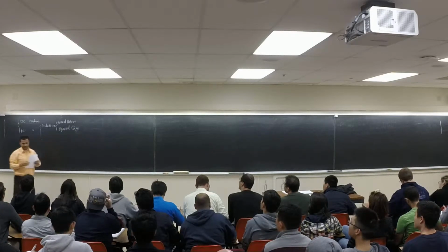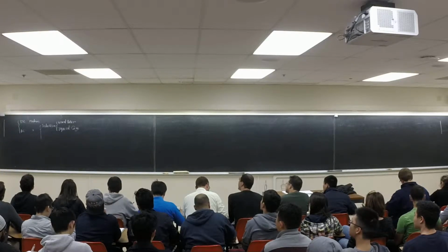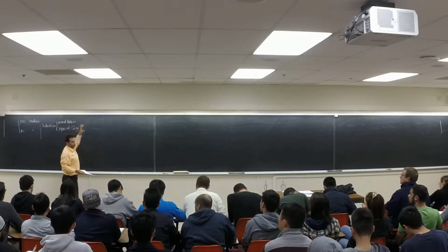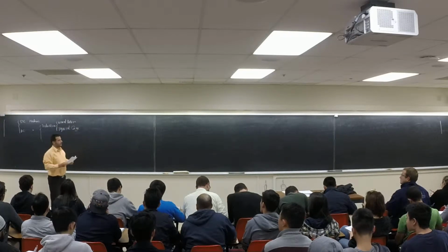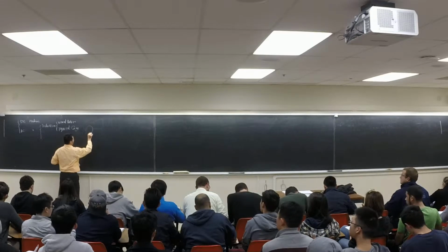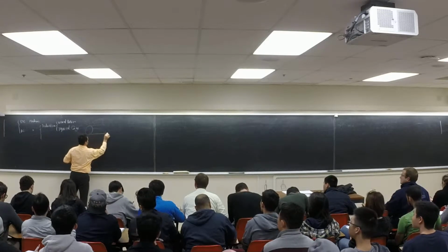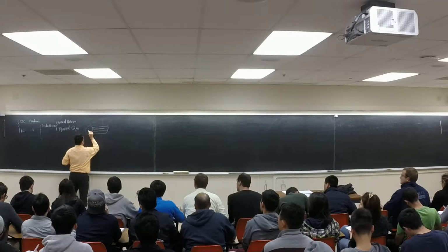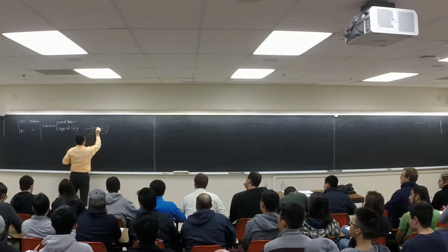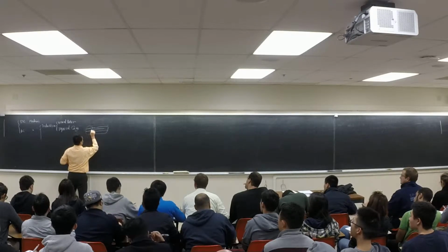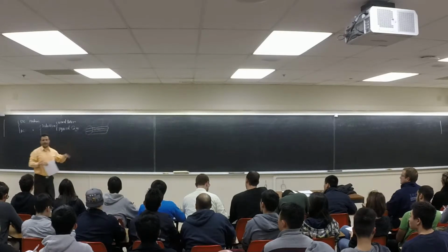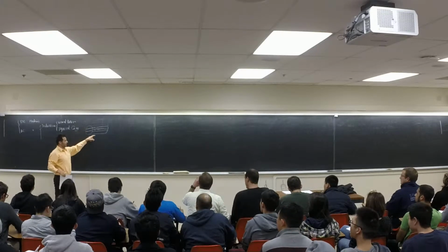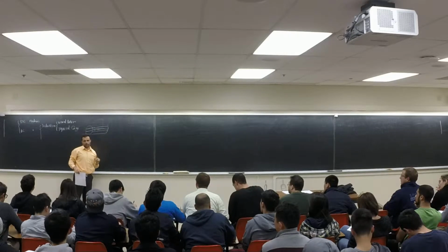So a squirrel cage, the reason they call it a squirrel cage is because if you look at the rotor, the moving part of this machine, there is a piece of iron, and there are copper bars like this. They call it a squirrel cage. You don't have any access to the rotor. The windings are shorted here.